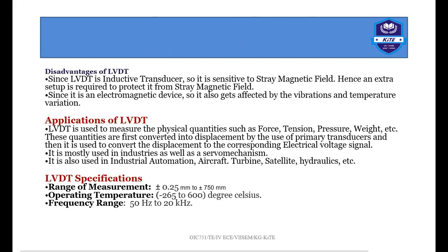Next come the disadvantages of LVDT. Since the LVDT is an inductive transducer, we have already seen this in the introduction part. It is very sensitive to stray magnetic fields. Hence, an extra setup is required to protect it from the stray magnetic field. It also gets affected by vibrations and temperature variations, because it has a very high sensitivity.